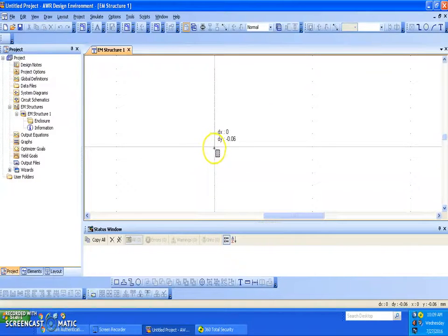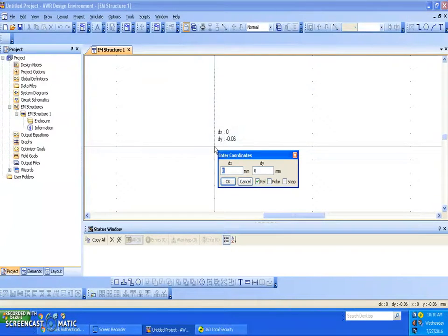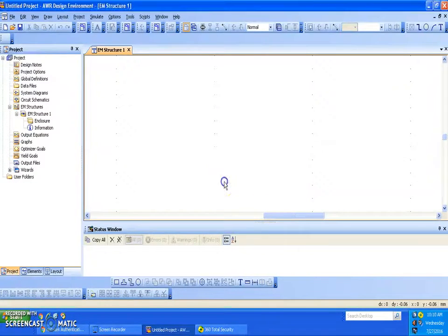So you are able to see that the starting point is at the exact center, at the coordinates x equal to 0 and y equal to 0. Again, to enter the opposite end corner values of the coordinates in a rectangle, click on the space bar, and in space bar now we are going to enter the value of dx and dy. The value of dx you can enter as 33 and the value of dy you can enter as 1.533 mm and click on the OK button.